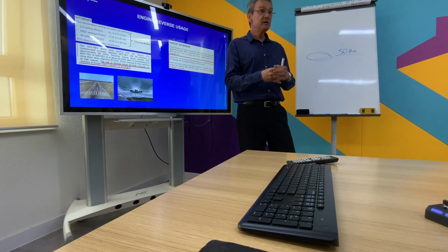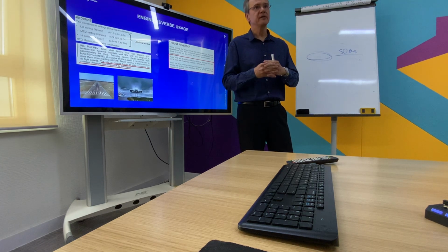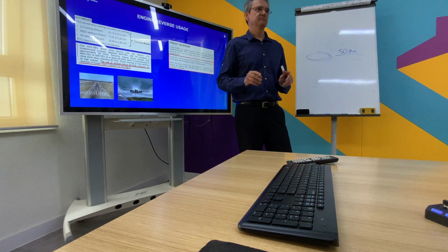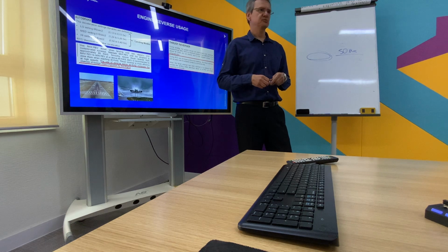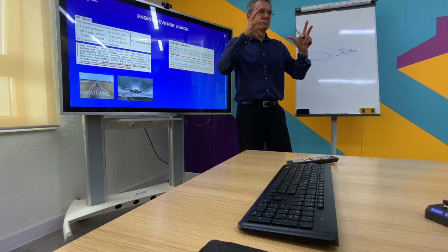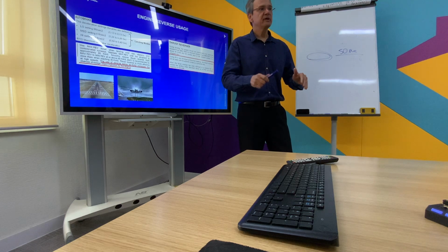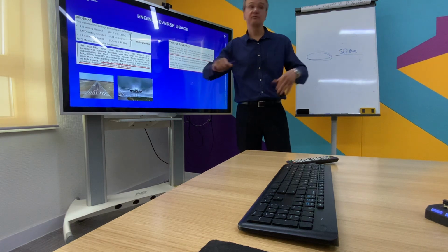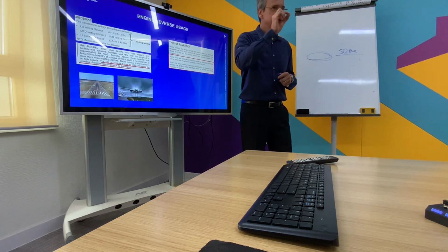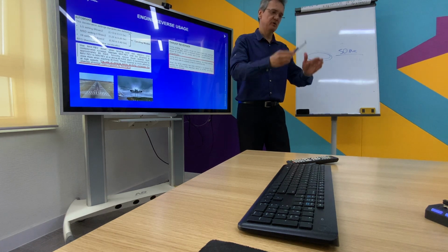Maximum reverse is really important, and it's a must if you are landing on a wet runway or a contaminated runway. So there's no discussion regarding this. Go to max. Yeah, but on dry runway, no need to do that. Only minimum reverse. And try to state it on the briefing, on your descent briefing, approach briefing. So configuration for landing is going to be minimum reverse, auto braking low, flaps 5, in case of go around flaps 2, flaps 4. But state this point during the briefing so as to keep in your mind that you're going to use minimum reverse for dry runways.